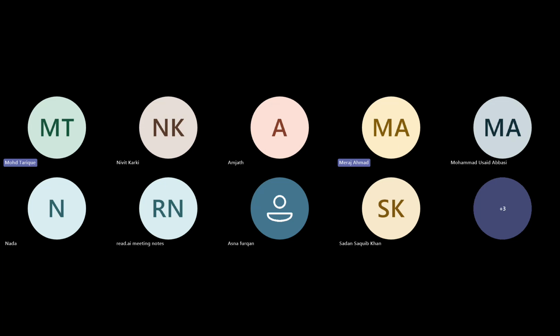So if you are using the Vivado simulation flow, go to add sources, and if you have a test bench, add it here and select create simulation sources, because it's not synthesizable, we put it separately.